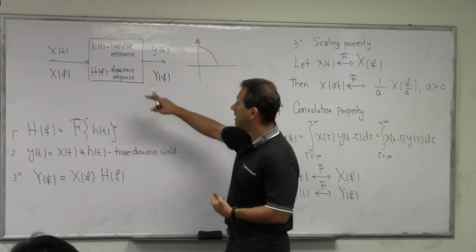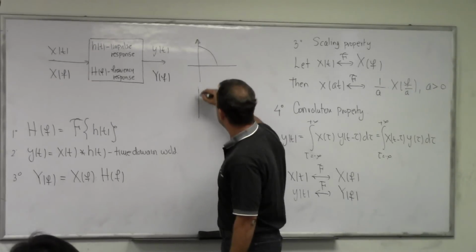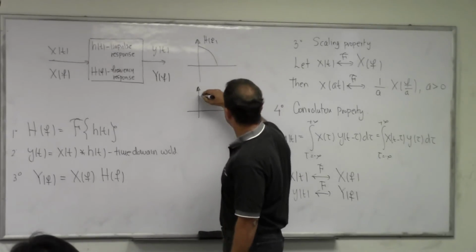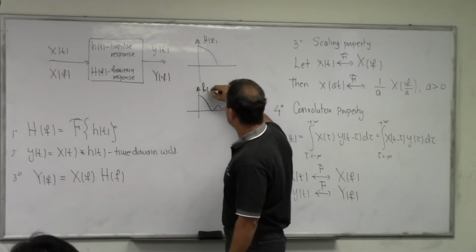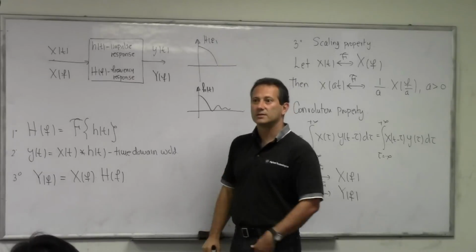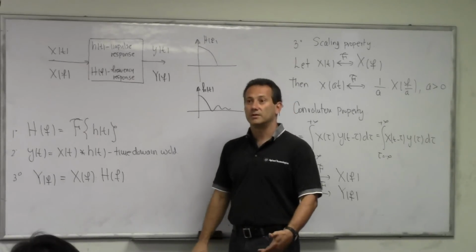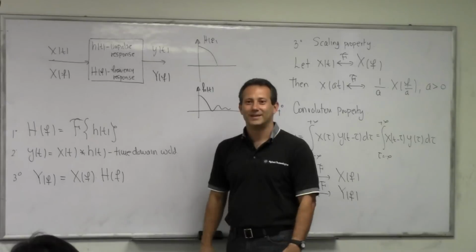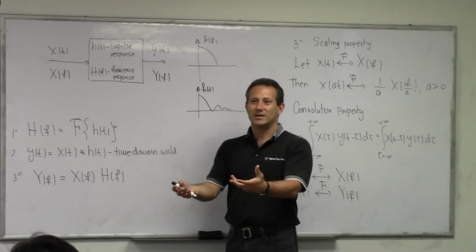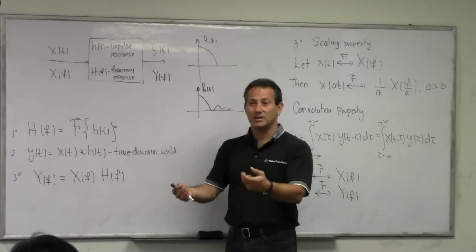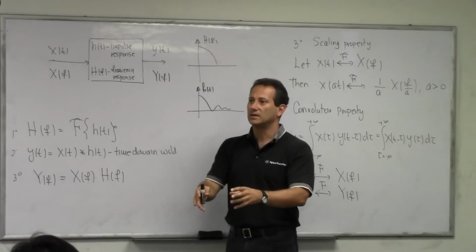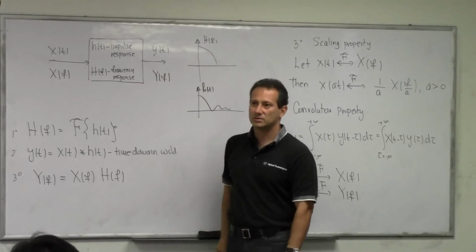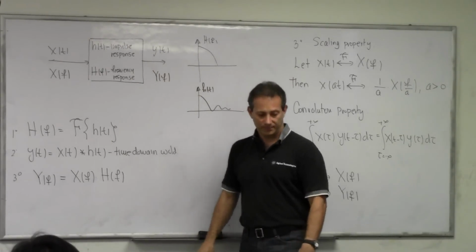I could have stayed in the time domain and you say, give me a low pass filter, and I say, here is the low pass filter. What is it? That's the impulse response, right? So if I give you this signal, what happens? Well, I need to convolve, right? And then this becomes really messy. And you don't know what is actually happening if you're just looking at it in time. But what is happening is very clear when you see it in frequency.